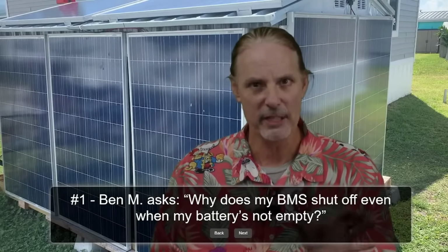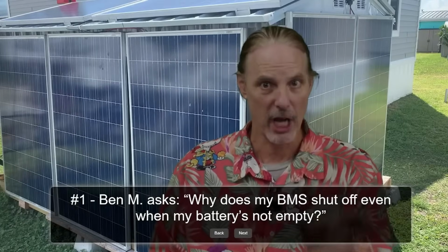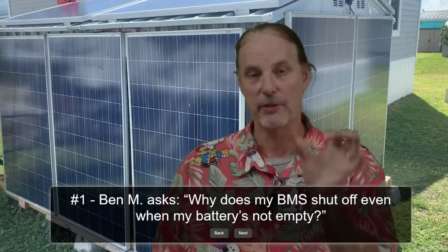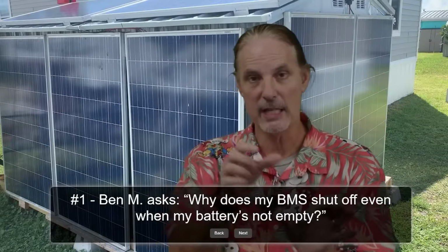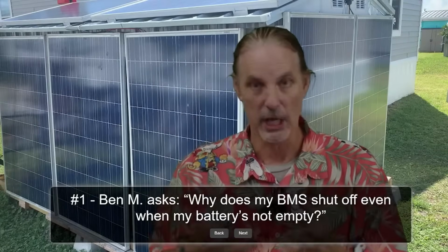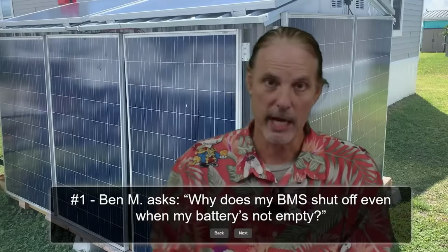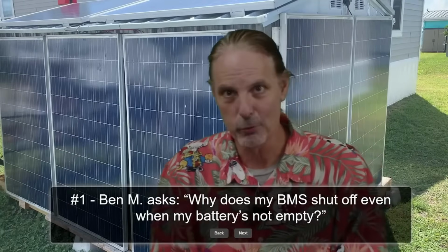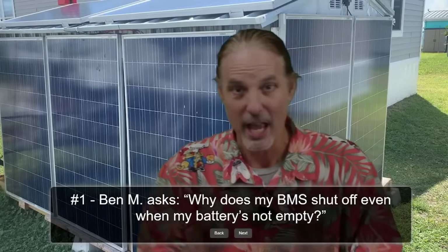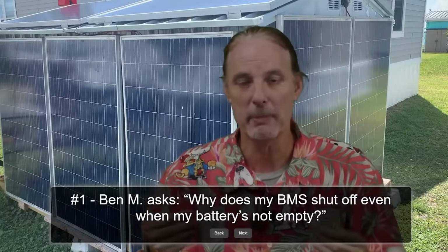I think I have a video out there on calibrating a JK BMS where I check the voltage first, and then you follow that by checking the amperage and calibrating it with a gauge of some kind, and you determine how much amperage is going in. You can't do it in reverse order because the amperage won't be right if the voltage isn't right. So you need both of them to be set for it to be truly accurate.